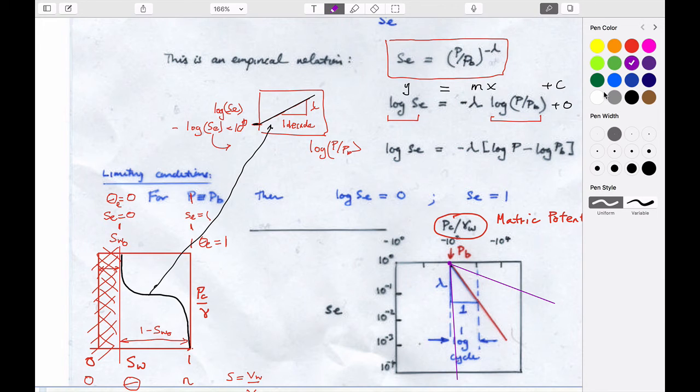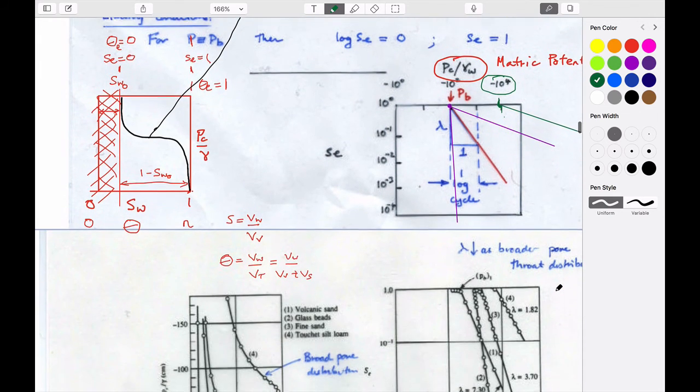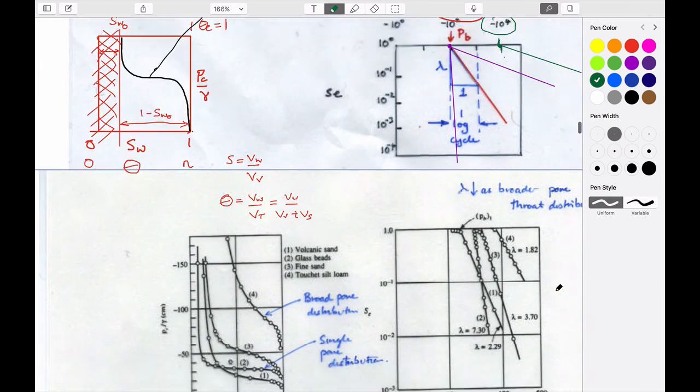If the intercept happened to be over here, you guys have answered these questions before, then this would be a broadly graded pore space where the biggest pore is smaller, right? You have to apply a larger pressure to push the bubble in, and therefore this is a smaller pore space that you have to gain entry. But once you get entry into it, then all the other ones are broadly graded and fill up slowly as you start filling it. Well, we've talked a little bit about that.